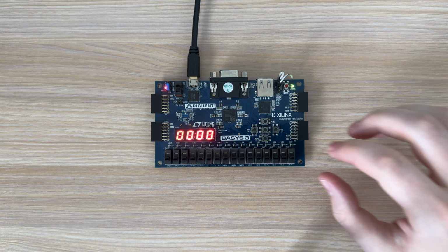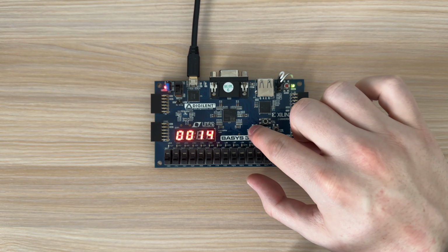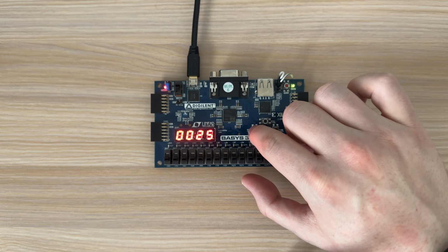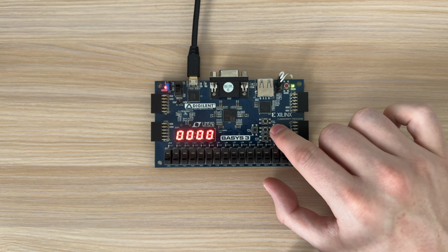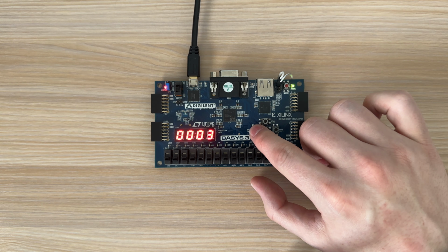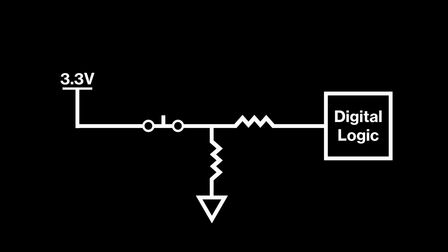When the left button is pressed, our counter goes up. If we press the button enough, though, we'll start to see glitches where our value goes up by more than 1. We can reset our counter with the right button, but we will continue running into random counting errors. This is due to voltage spikes when our button is pressed. Analog buttons are noisy, meaning their values aren't instantly stable, and can bounce rapidly between on and off. The code that we have doesn't account for this.